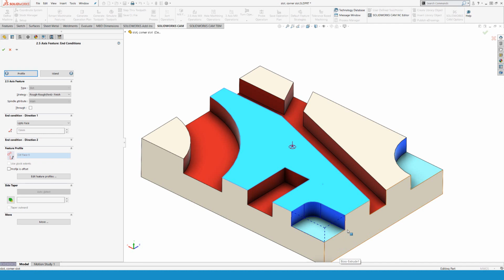And you can see, hopefully, that lines in here are solid lines, whereas these ones are dashed and open lines, meaning that this is an open segment. The tool can enter and exit freely. There is no collision. And when it's a solid line, then it knows that there's material behind it.